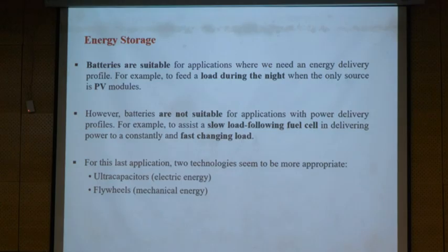When you increase the generation from renewable energy, the conventional ones decrease one by one. So 10 goes to 9, Z over 10 goes to Z over 9, Z over 8, and so on. As much as the renewable energy increases, the conventional generation decreases and the impedance increases. When the impedance increases, the voltage changes will be more affected by the load changes.